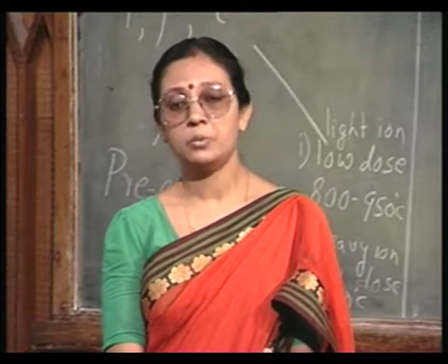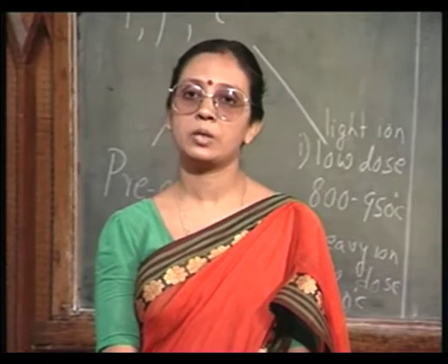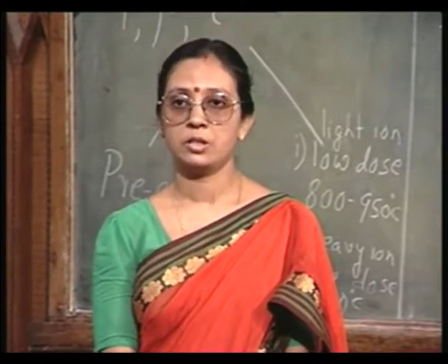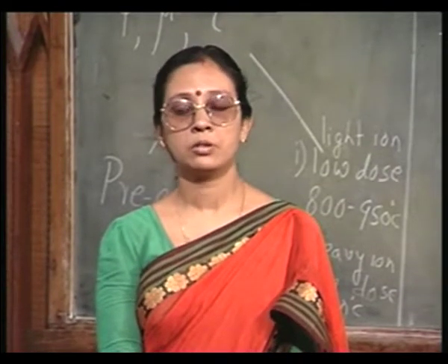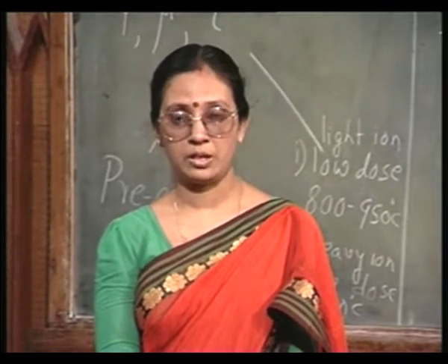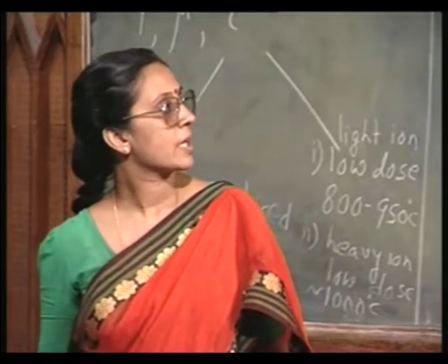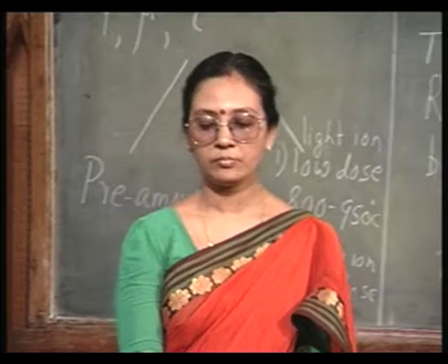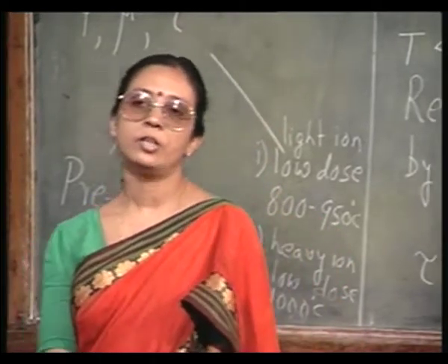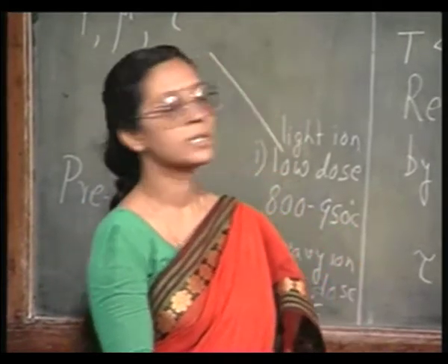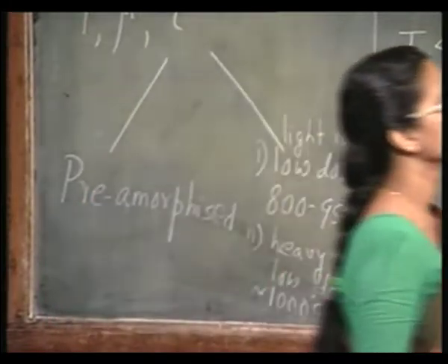I mean, you can live with probably a low lifetime, but you cannot live without the full carrier activation, or at least 90% of carrier activation. Okay. So, first of all, let us talk about phosphorus implanted in silicon.